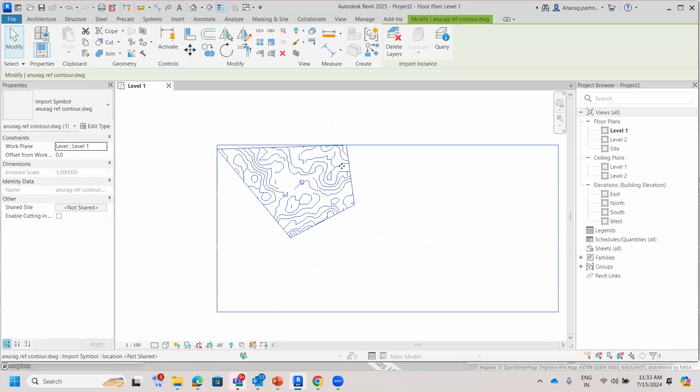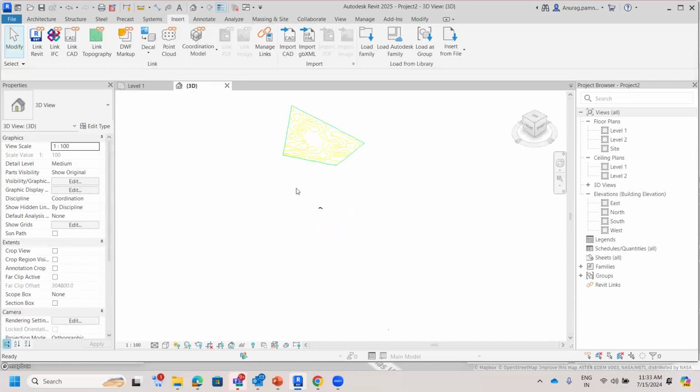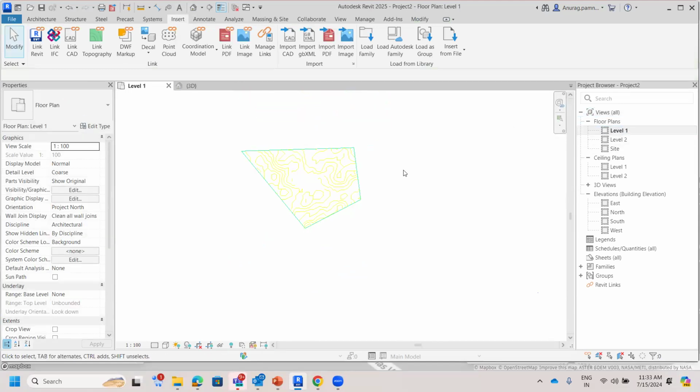Now this CAD file was having certain data with respect to its elevations and spot elevations. So first thing is I have to acquire those points onto my Revit interface to start working with that particular domain, that particular contour file. Right now, if I just show you the 3D, it is something like this, which is way beyond the height of what our levels are set. So it's at a certain height, the file has appeared over here. We have inserted it onto level 1.